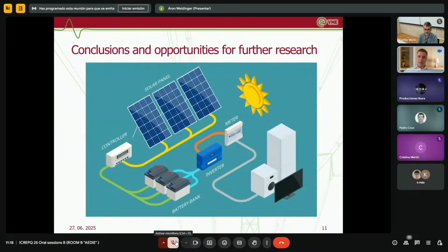To summarize, HVDC links didn't significantly improve global synchronization or reduce cascade size with this modeling approach compared to the reference case. However, HVDC links did not notably worsen synchronization, but they also did not significantly reduce the average cascade size. Interestingly, the Scandinavian region consistently showed the weakest synchronization, which in fact also has the most HVDC links, which could be an explanation for slightly weaker synchronization.